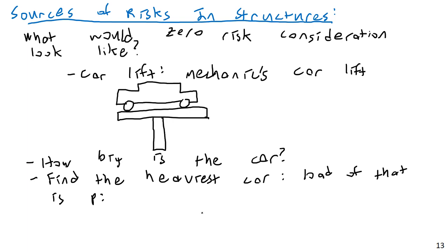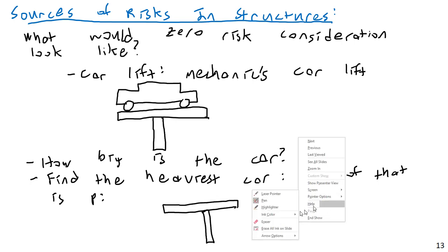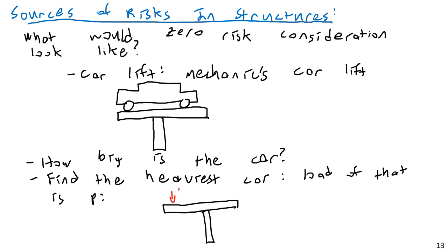And then maybe I design it like this. I have a column in the center, and then I have a beam on top of it, basically a double cantilever beam. I have a point load P over 2, maybe I assume half of the load is over here, P over 2, P over 2, and then an upward load P here at the support. Well, that's all well and good, and so let's say I do this, and then based upon this, I size the beam using just mechanics, even just level mechanics of materials type knowledge. I size the beam based on bending and shear.